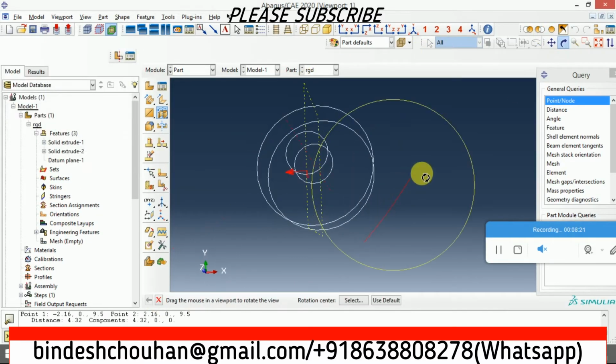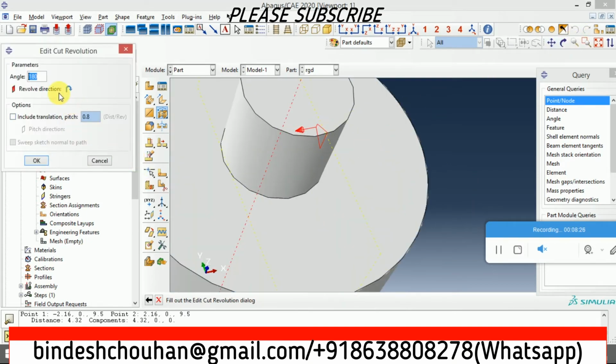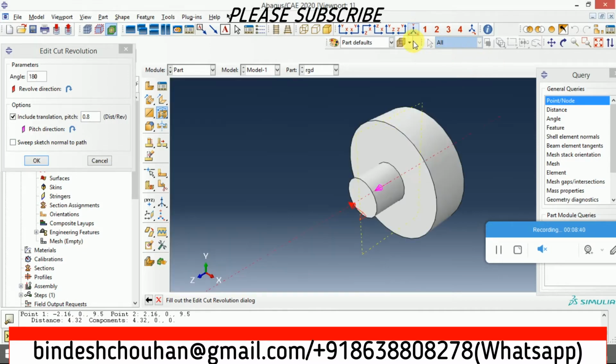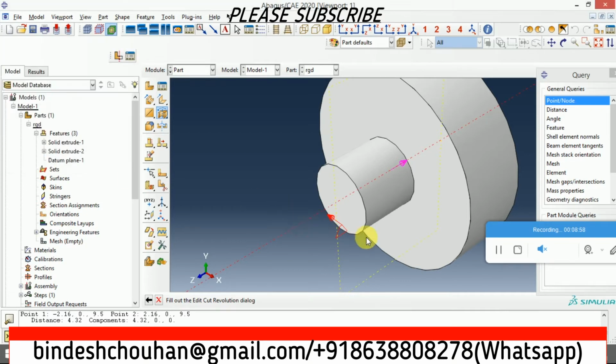Over here, as you can see, this is the cut we have made. Now it is asking me for the angle and also the pitch. So pitch I'll keep 0.8 because M5 pitch is 0.8, and the angle you'll have to do trial and error. Also you'll have to flip the direction in which it should be pitched, or it should move the thread. So this is the direction, because I want it in the downward direction. Pitch will be 0.8. I'll keep it approximately 1500 angle, so I hope it will cut.